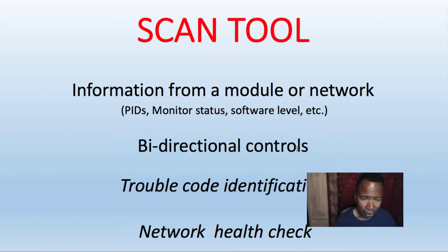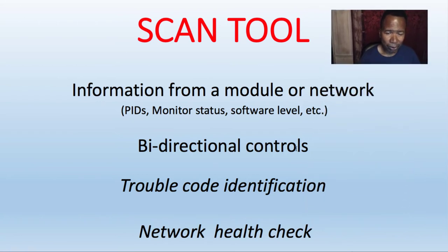A scan tool should be able to read trouble codes. Now you've got code readers and scan tools. A scan tool can do everything above plus read codes. A code reader just reads codes. And there's network health check. That's on more advanced scan tools on a network system.